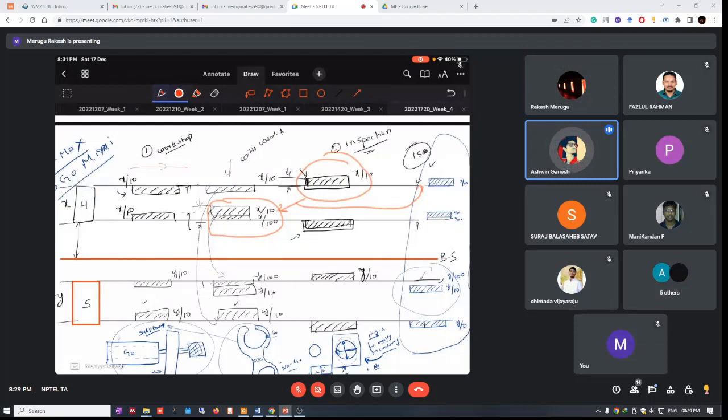Okay, sir. And for example, if we have a hole which enters both the no go and go, which means it is a larger hole, sir? Correct, it is oversized. Yes. If you carefully see, this is the area where we are actually accepting the products. It is more in inspection, less in workshop. And if you take ISO, it is in between these two.